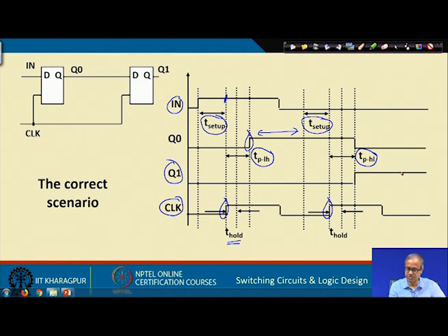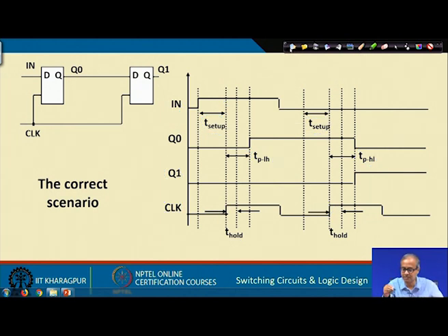So, this shows the basic requirement of the timing constraint, which you see once more carefully. You see, this is your total time period of the clock, starting from here, the first stage up to the next stage. Now, within the time period, what are the things that are included? You must have one setup time, you must have this propagation delay, and of course, hold time and propagation delay can overlap. So, setup time and this propagation delay are the most important delays that must be included here.